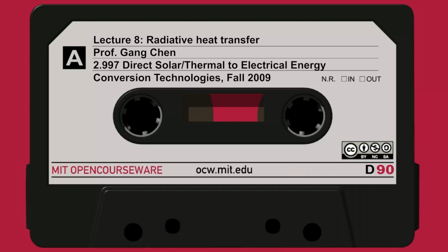So that's the case when you use a photovoltaic: there's a band gap, and photons below the band gap do not excite electron-hole pairs, so that part is completely gone. And in fact, for that part, it's better to just filter it out if you can do it cheaply. Why? Because if your solar cell absorbs it, you will heat up the solar cell, and usually when a solar cell heats up, the efficiency drops.